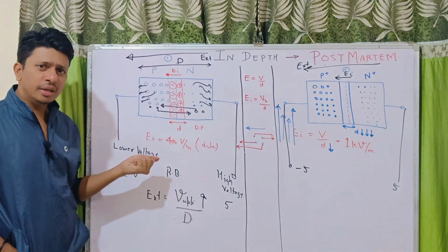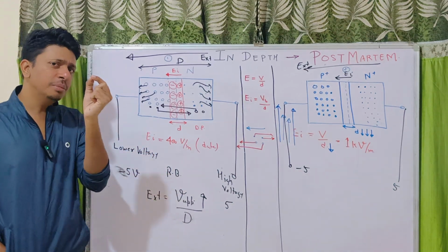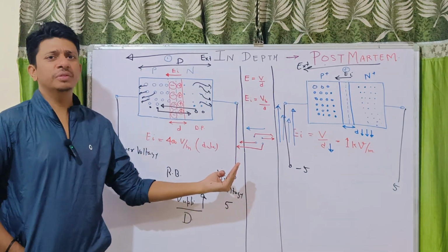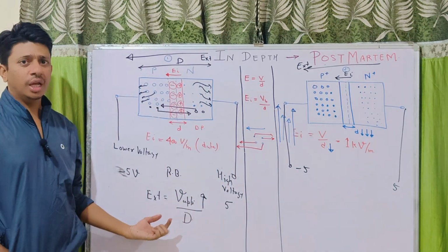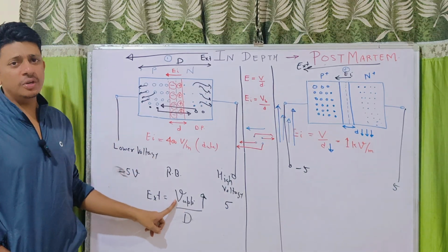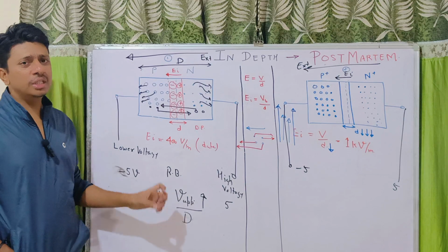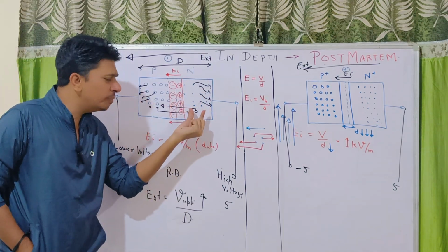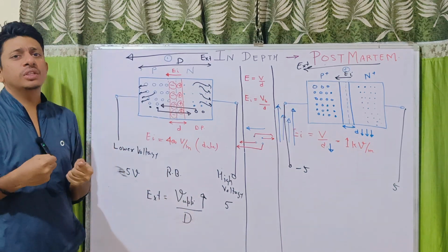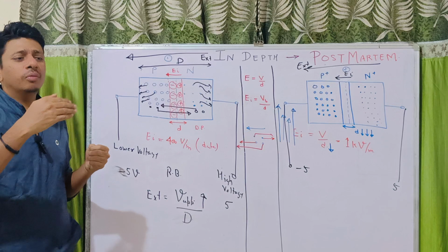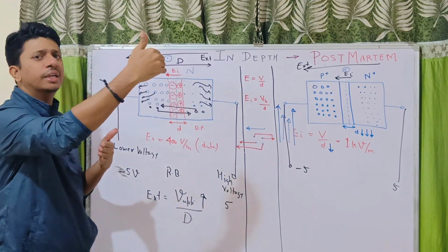In order to get a sudden breakdown we need a minimum electric field, and this minimum electric field is not achieved by this configuration. In this case breakdown is possible only because of the applied voltage, and this applied voltage is such that the electrons, these minority carriers, get so much energy that they break the covalent bonds one by one, electron 2, 4, 8 and so on.